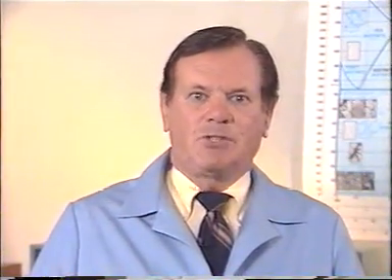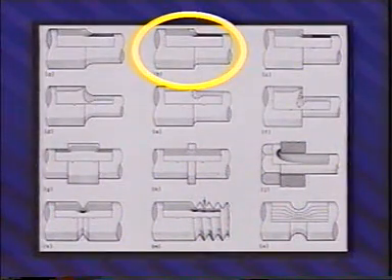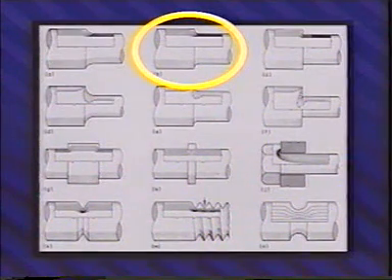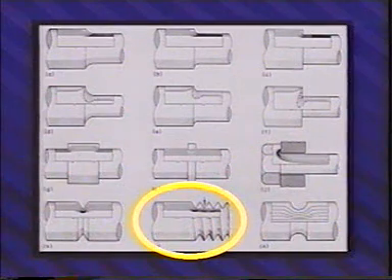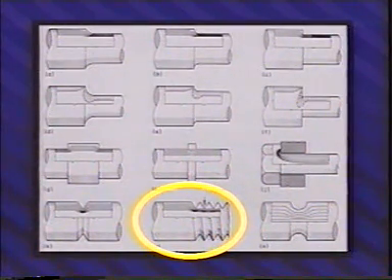Stress concentrations affect the fatigue behavior of different materials differently. For instance, relatively brittle materials are more susceptible to the effects of stress raisers than ductile materials. And the flow and distribution of stresses change with section size or shape. In parts with a decreasing fillet radii, for instance, the stress increases at the point where the section size becomes thinner. In threaded components, a single notch introduces a considerably greater stress concentration effect than a continuous thread.